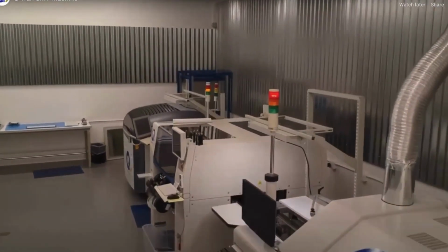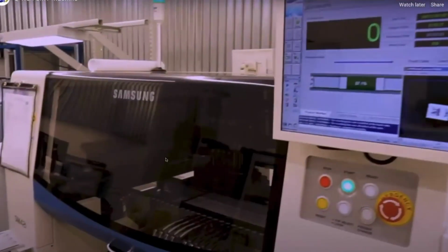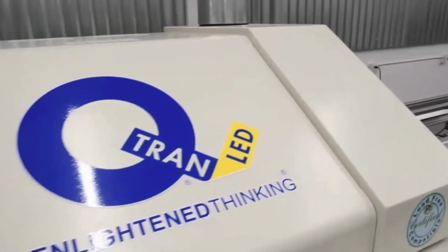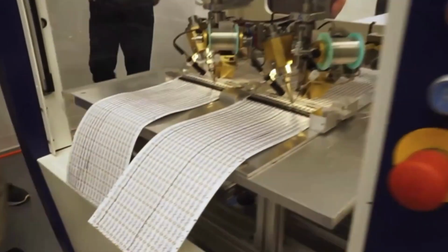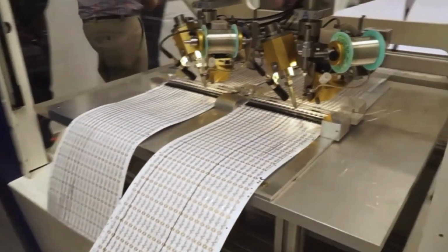Starting at the far end, and we go a little out of step in this video, you have stenciled sheets, which are the LED strip itself. The LEDs are populated on the board by a robotic arm that's actually working at about 1/5 speed. So this is just for the video, obviously. See how it's picking the LEDs? It's a pick and place, sort of, off of the spool, setting them on the PCB. The PCB is then sent through an oven to electronically and heat secure.